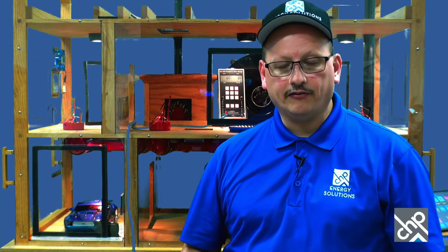And so when we did all this demonstration with the duct leakage, the only thing I had on other than the fireplace to show the smoke was the air handler fan. So basically you could go into a house, set up in your natural conditions, put your manometer hose to the outside in the middle part of the house, and then do your baseline, and then turn on the furnace fan. Sometimes you can turn that on directly. Other times you have to turn the heat or the AC on to get the fan to come on. It depends on the thermostat. And if you've got AC, you want to turn the AC on, you can see the biggest pressure. Just turn on the fan, watch your manometer, see what the pressure changes.